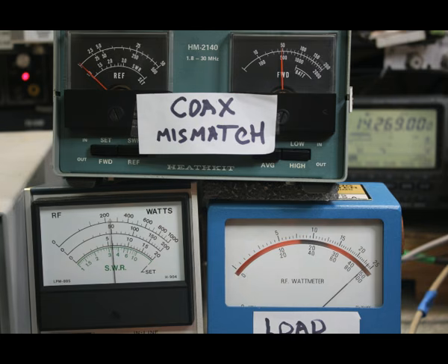Now, if these tables that everybody uses, and all these theories bouncing around, and these people with pictures in their heads that the power bounces around in the coax, are right, we're going to expect that this loss table by Fire Stick, that we can commonly find everywhere, will show that kind of loss when we terminate the cable in a 10-to-1 standing wave ratio and apply the same amount of power. So let's do that and see what happens.